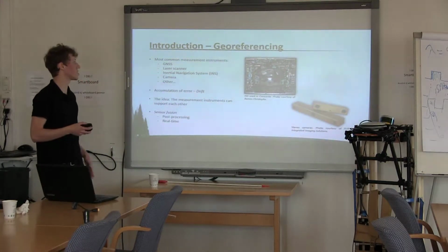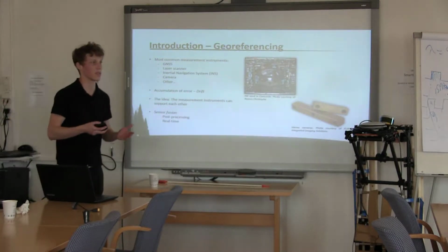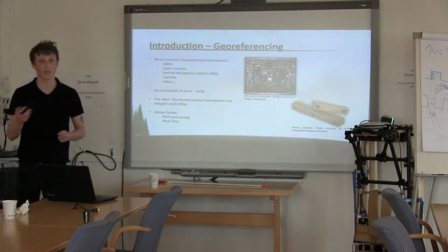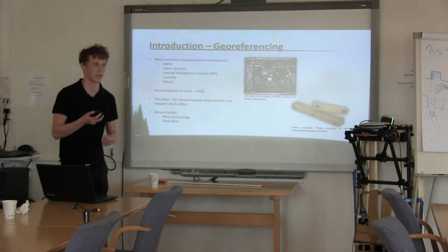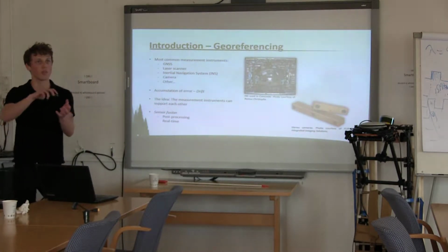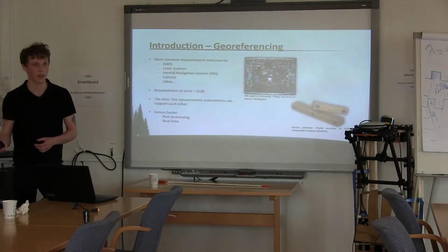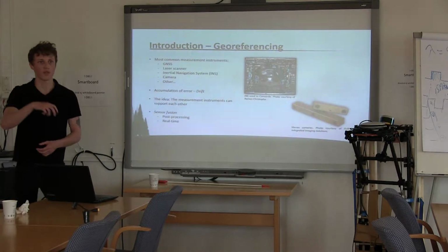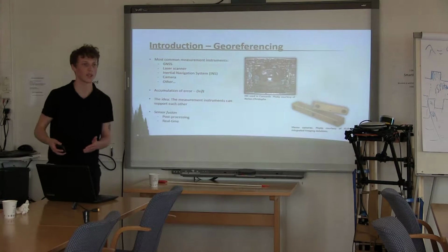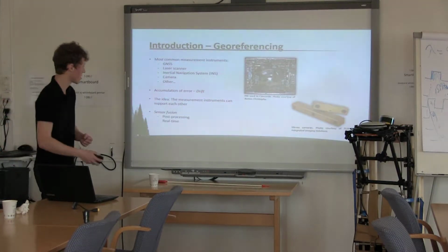And for example, the inertial navigation system, which is very, very commonly used in airplanes, aircrafts, I mean, suffers from accumulation of error, or drift, as it's called. And that comes from the INS being composed of gyroscopes and accelerometers. So it measures accelerations. And to get position from that, you have to integrate twice. And this induces an accumulation of error over time, which gets worse and worse.